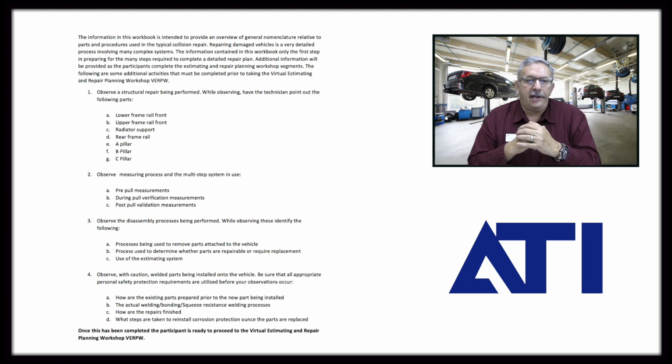Then the fourth one, and this one I'm going to give you some cautions on. We want you to observe some welding processes being completed. However, I want you to make sure that you're protected. If you're right next to it, wear a welding jacket, at least some type of leather coat to keep you from getting weld slag onto you, and make sure that you have the appropriate eyewear or a welding helmet so that you don't hurt your eyes. But I want you to actually be able to experience what that technician is doing to install the parts.